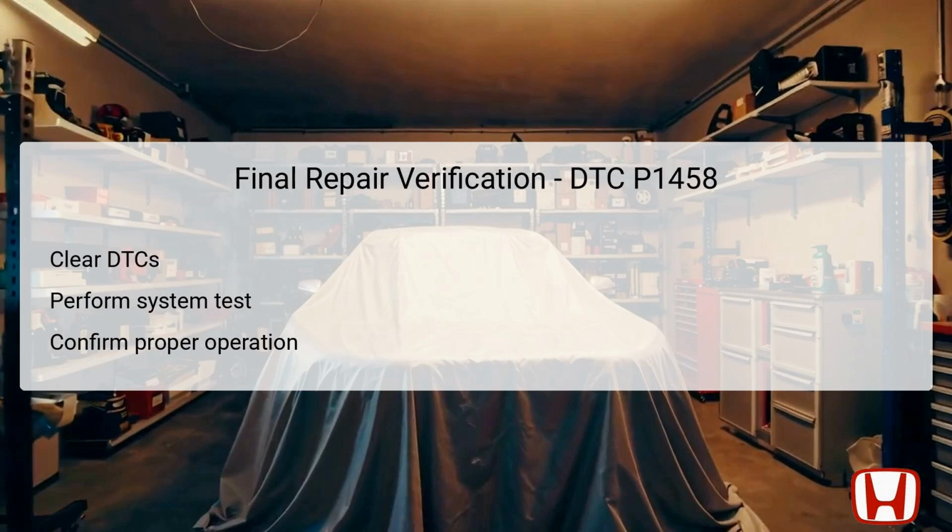After completing all repair tasks related to DTC P1458, it's essential to conduct a final verification of your work. Start by clearing any diagnostic trouble codes, DTCs, that may have been stored in the PCM following your repairs. Next, perform a system test to ensure that the vehicle operates seamlessly and that no new DTCs are triggered.